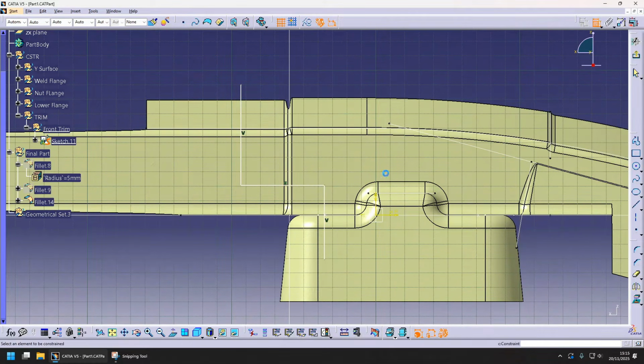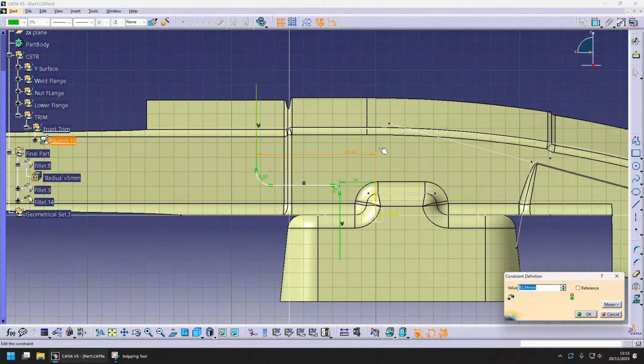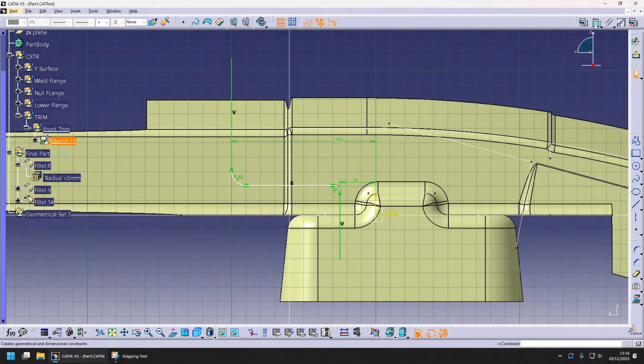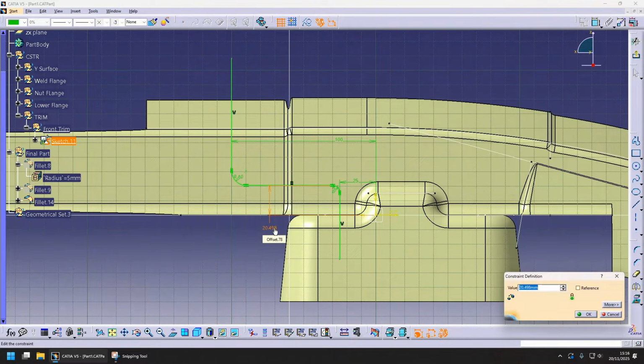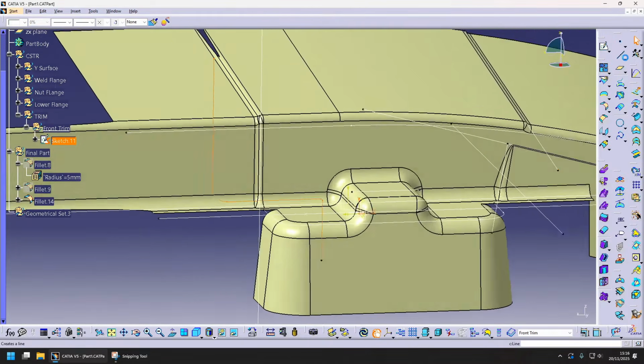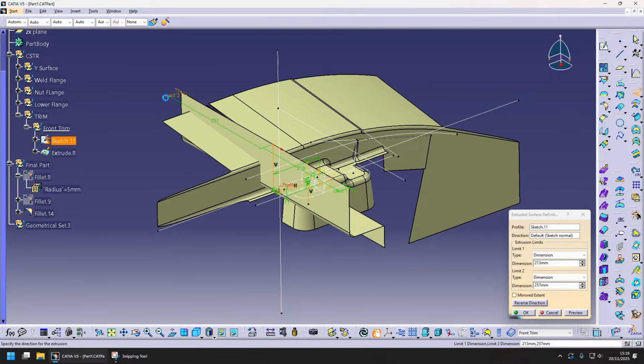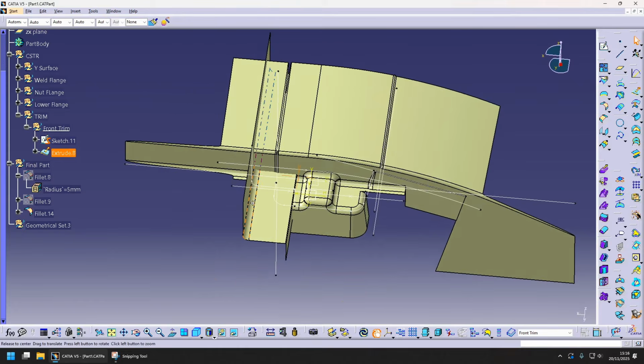We just need to worry about the edge to the left, because we're not gonna use the right edge. We're just gonna use it to connect it to a different surface. Right, make sure we constrain it well. Okay, this corner here we can make it as small as possible because we're not gonna use it. Right, now we extrude this in Y and start working on the next sketch.